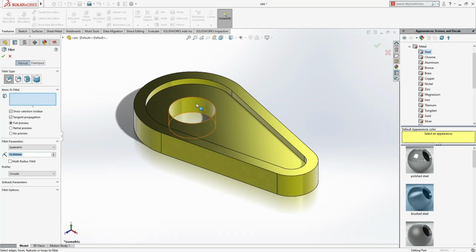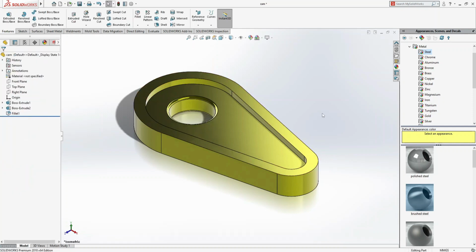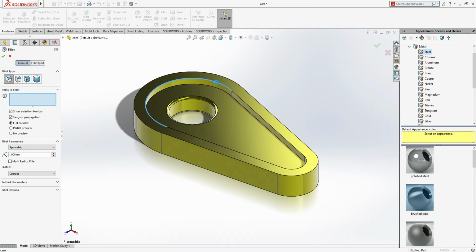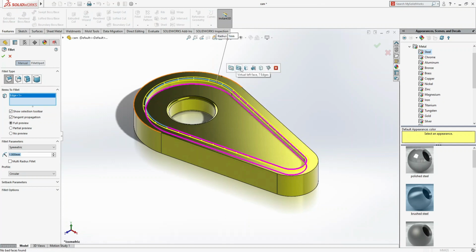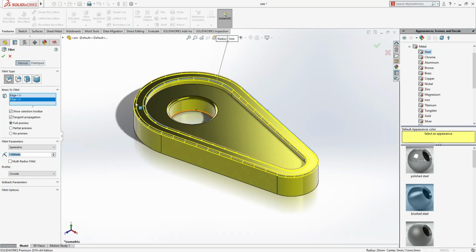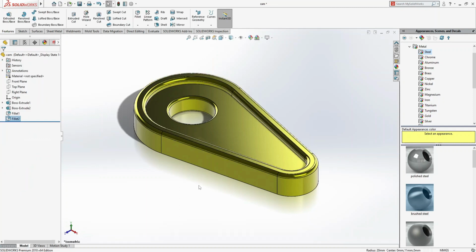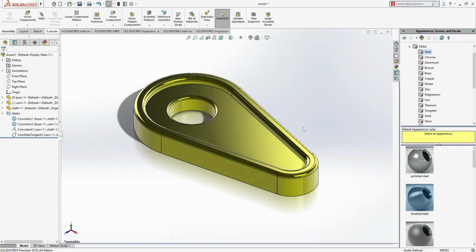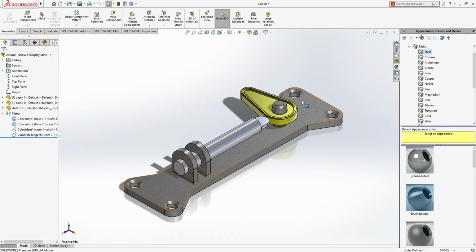And one more thing, fillet, one here and the one on the downside. This is going to be 1 mm and okay. Control S, fillet again, and I want to select this side and this side. 1 mm, yes, 1.5 mm, and Control S to save it. Let's close and yes, change in assembly. Control 7 for isometric view.